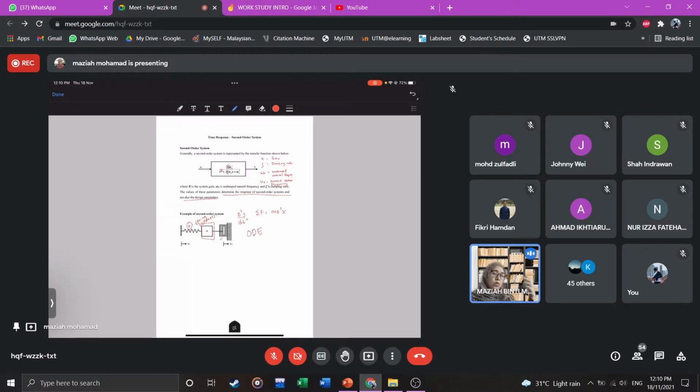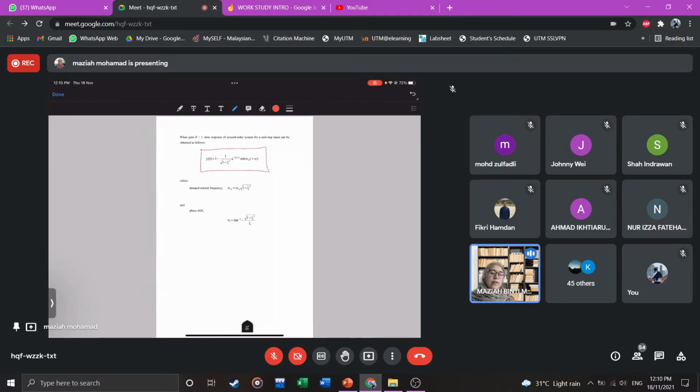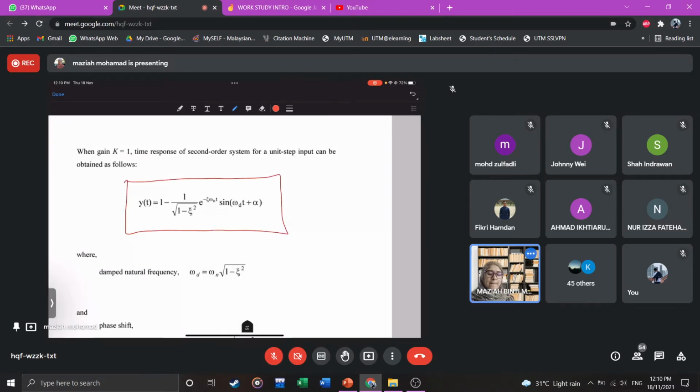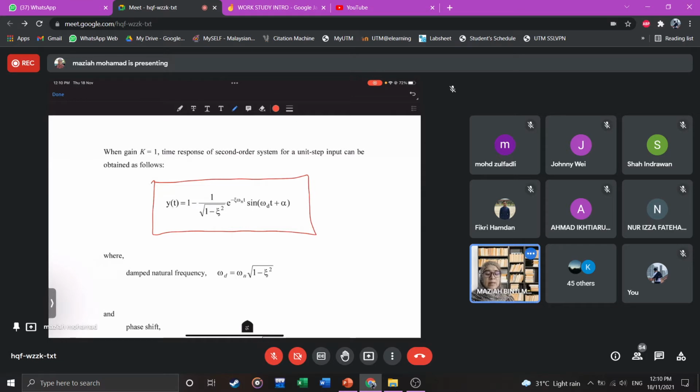After you inverse the partial fraction part, after you already determine A, B, and C, you are going to inverse that, and then this is the general time response. General here means we do not determine the value of zeta, omega n, alpha, and omega d yet.